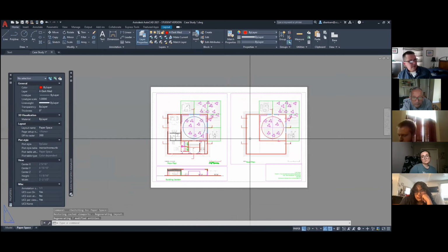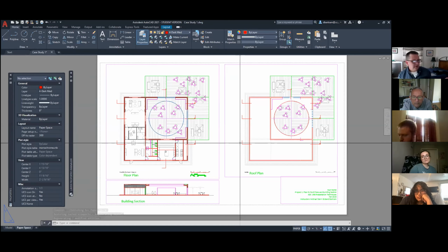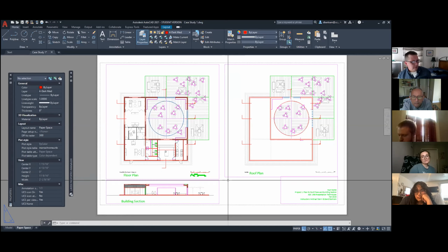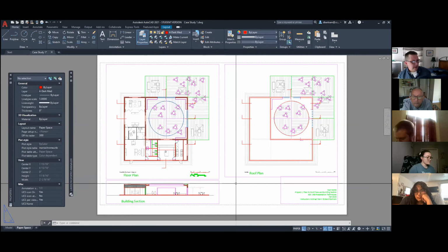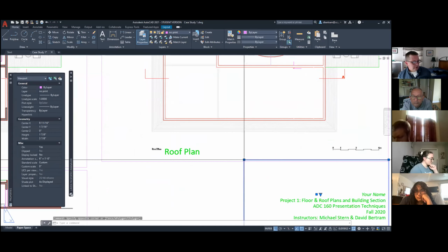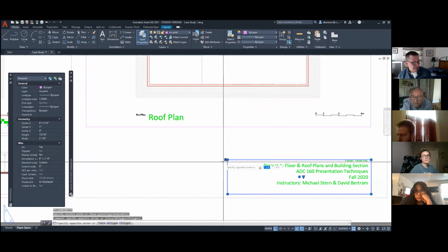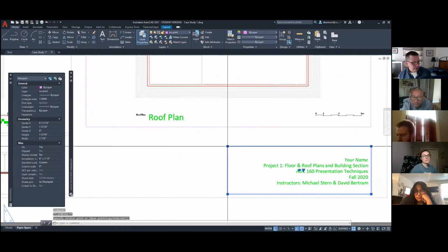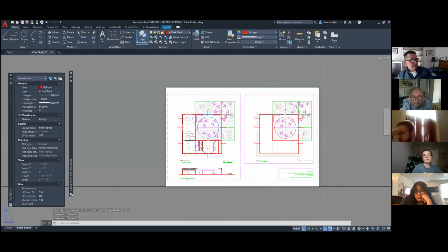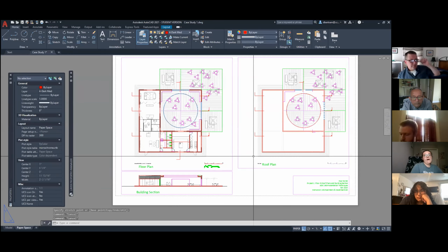But when you're in paper space, go easy. Don't mess around with these things. Just keep an eye on everything. You don't want your viewports overlapping. Keep things nice and neat in paper space, and proceed with caution. It takes practice to get everything aligned, and once it gets messed up, it can be confusing.